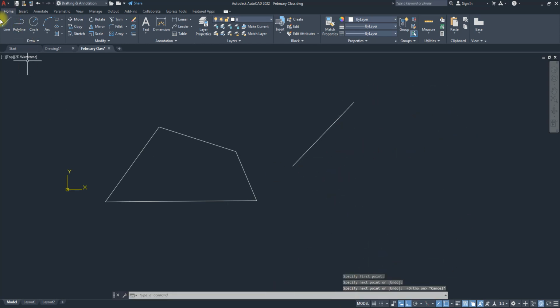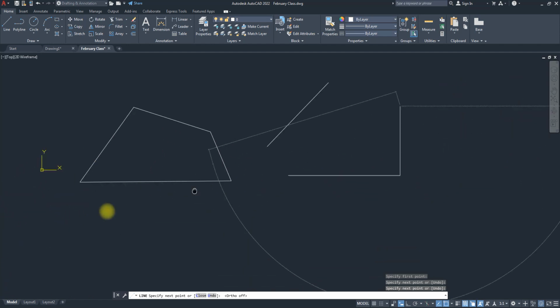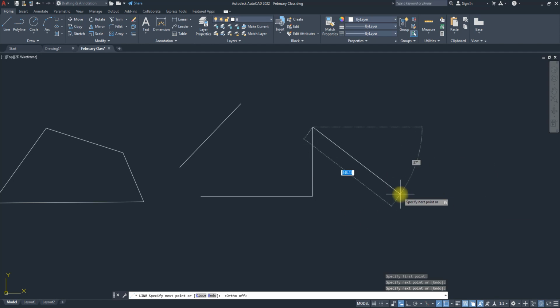So you notice if you create your line, you have all this construction line all around. For me, it's distracting, and it also makes my system slow. It really makes systems slow; planning and doing this drags the system a little bit. So what I do is I actually do not use this. The tool that makes us have all this construction line is called dynamic input. It has a shortcut, F12. But this is where you get your dynamic input.